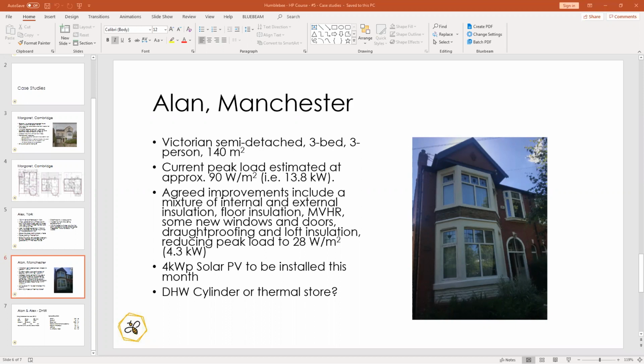And with heat pumps, every time they change over from doing one thing to another, you're getting losses anyway. So sometimes it can be easiest just to run it at one temperature, and then particularly when you've got PVs, use that power to raise the temperature there. Obviously in the winter, you're not getting so much off the PVs, but most of the year you'll be getting something. Great. Okay, thanks.